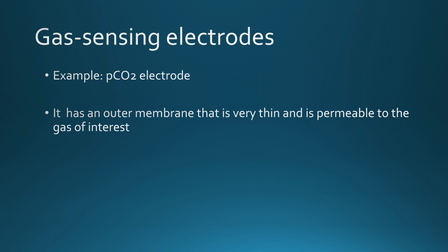And the opposite is true in alkaline solution. The exchange will be in the opposite direction. The protons will get out and the sodium will get in, and that will also result in a change in potential that, when measured, will give the value of the concentration or the activity of the hydrogen ions.